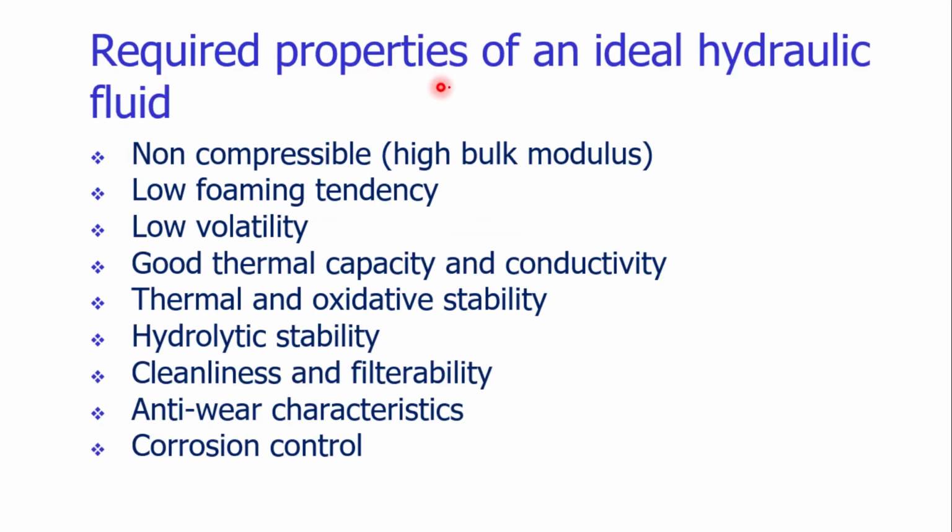There are certain properties that an ideal hydraulic fluid should have. The fundamental property is that it should be non-compressible. It should not compress, so that it will transmit the power efficiently. It should not form any foam during the operation.